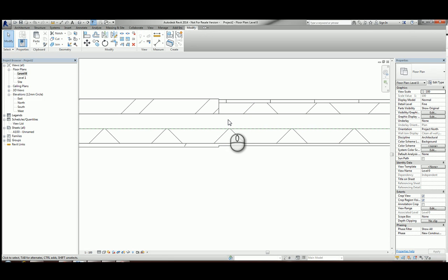Now it depends on what kind of project you're working on. I've always done a lot of housing, and this has always suited me. But for large commercial projects where you're setting out thick wall construction with, say, light gauge steel with 140mm studs, where you're setting some beams up in between it, quite often you want to use the centre of the core, because you can set this out to grids, which then you can place your vertical wind posts and beams and columns onto that same grid. So I'd use that. But in this case, I would quite often just use a core face exterior.